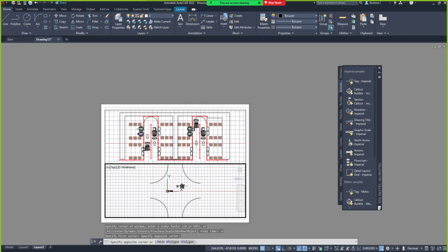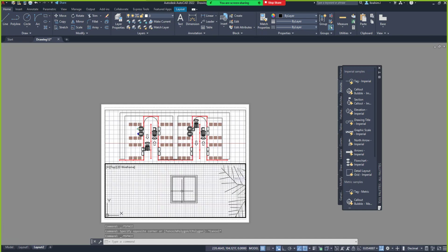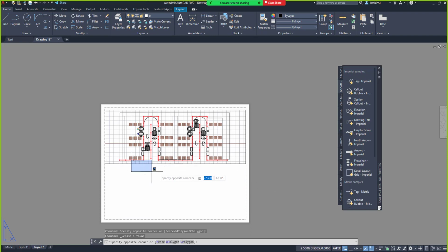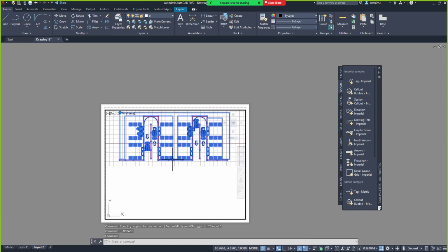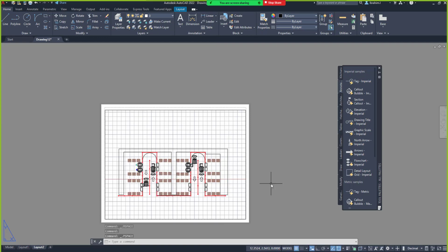That's exactly what we have on the screen. If you have something else that you want to display here, I click outside, go back into my model here, and then I adjust the view as well. Place my design here, and then I click outside. Any viewport you select will surely work, right? I delete one of them and then I adjust my viewport back to normal, which is my single viewport. Now I can decide to go back into my design and place my design properly, right?